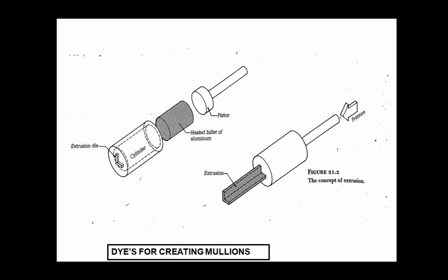So basically those sections and mullions are created using a process called extrusion, right, where the material is pushed through a die. To break this down to the kiddie level, it's almost like the Play-Doh. You know how it comes with all those extruders and pistons that force the heated aluminum through a die, and it comes out in the extruded shape. Okay. Cooled.